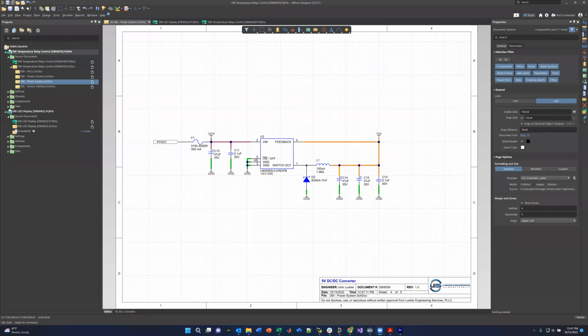So some of you already have had an LM2595 as your DC to DC converter. So this is pretty much the exact circuit you would be using for a 5-volt DC to DC converter. It's good for about an amp. It uses a simple part. It's a one chip solution. We have a power port. This is right here. This comes off of this wiring panel, and you get all of these because when you get Altium, some of these panels are not active.